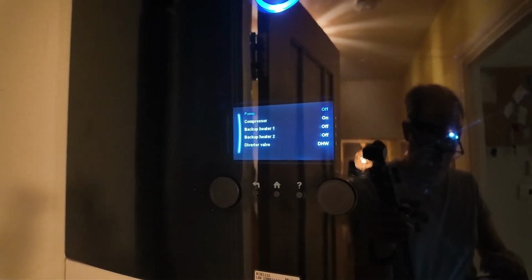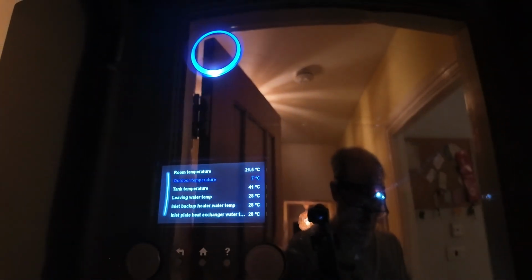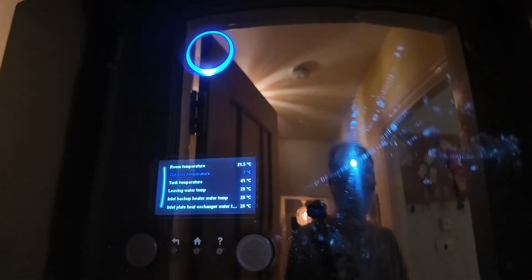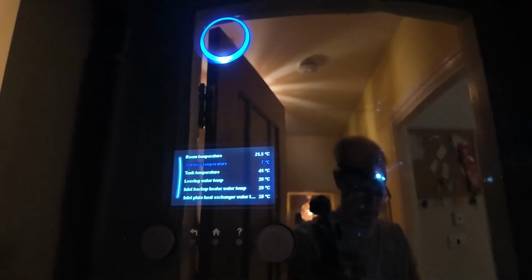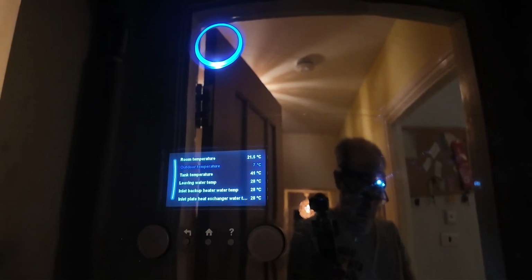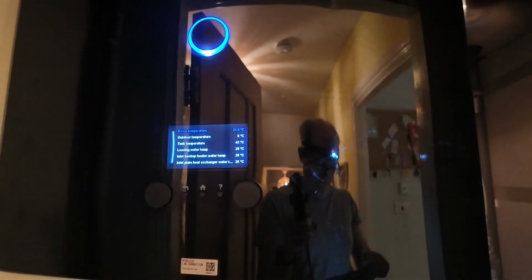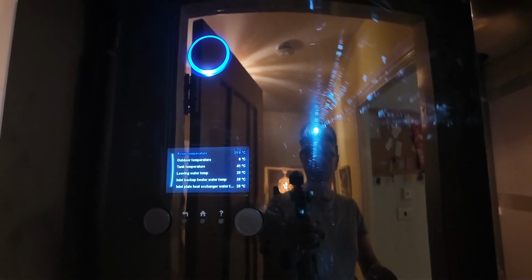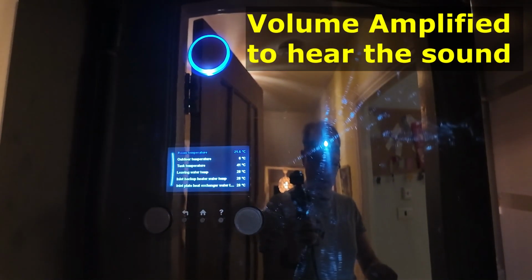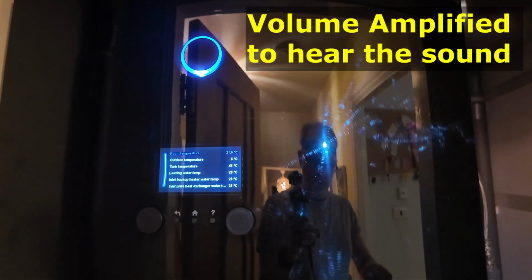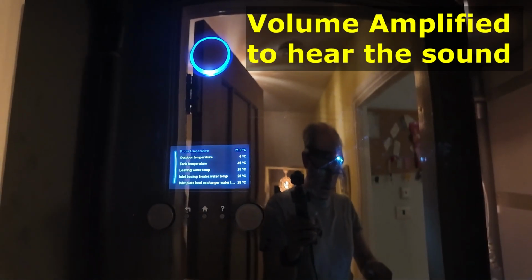So what's the flow temperature at the moment? Leaving water temperature is 28 degrees, but that's not being sampled with a pump. So let's just see, 24 degrees discharge temperature on my diagnostics. 29.5 degrees discharge temperature. Pump should come on now. But don't.